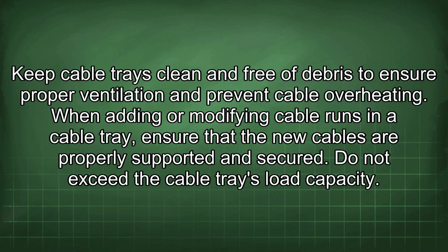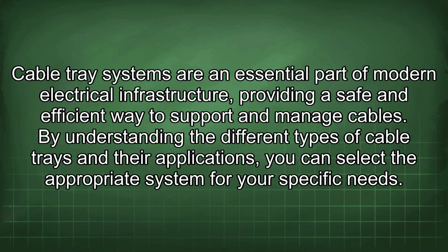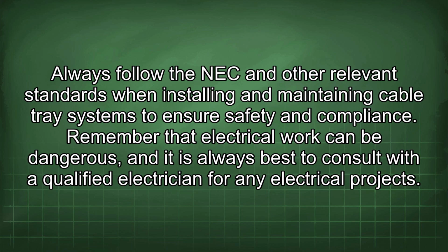When adding or modifying cable runs in a cable tray, ensure that the new cables are properly supported and secured. Do not exceed the cable tray's load capacity. Cable tray systems are an essential part of modern electrical infrastructure, providing a safe and efficient way to support and manage cables. By understanding the different types of cable trays and their applications, you can select the appropriate system for your specific needs. Always follow the NEC and other relevant standards when installing and maintaining cable tray systems to ensure safety and compliance. Remember that electrical work can be dangerous, and it is always best to consult with a qualified electrician for any electrical project.